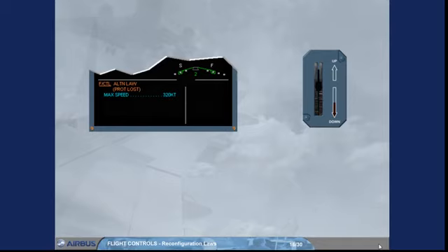Under alternate law, when the landing gear is extended, the control law will degrade to direct law. You will get an ECAM caution as shown, and additional messages on the PFD. We will study them later on. Note: if the control law is degraded to direct law before landing gear extension, additional information is shown on the engine warning display. This additional information is cleared after the landing gear extension.